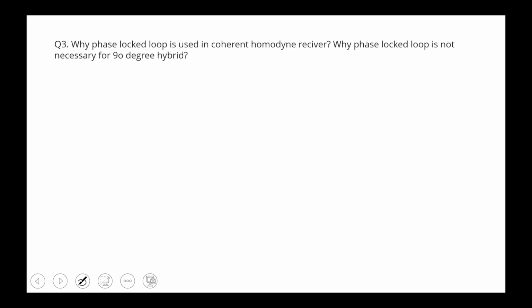So in this way we use the phase lock loop to track the low frequency phase noise. There is very low frequency phase noise which cannot be detected at the output side, and it will affect our signal on the detector side. So by comparing through the phase lock loop, we correct that and make phi nt equal to 0. Understand?